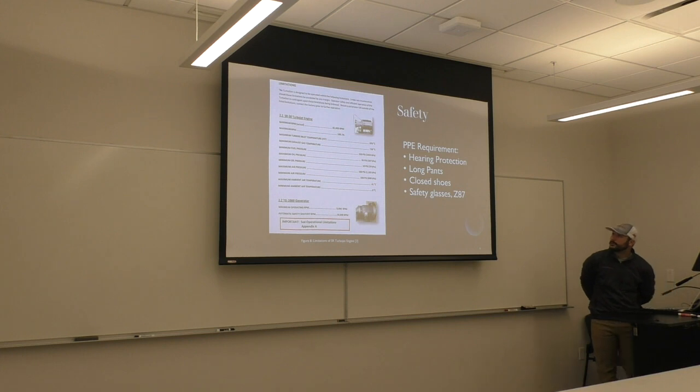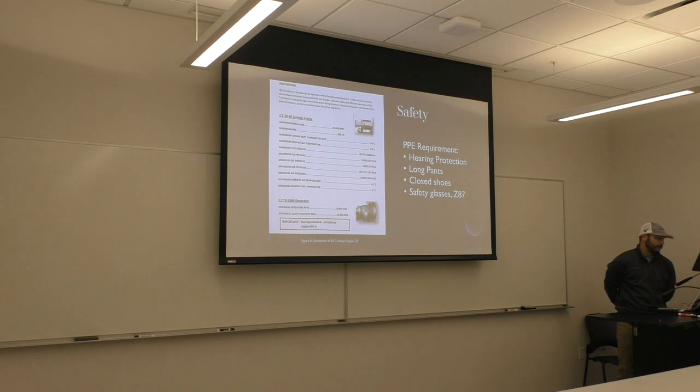For safety, you need hearing protection for this experiment, long pants, closed shoes, and safety glasses. And this picture shows the limitations of this specific jet engine cycle that we'll be using. You don't want to exceed 80,000 RPM or 106.1%.